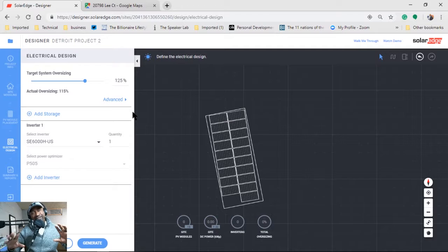365 days of irradiance, because in the summertime you have direct sunlight and it's high in the sky, but your modules get hot and they don't have as high a voltage. In the wintertime, you don't have as much irradiance, so they don't produce as much current, but you can have a scenario of cold weather. Cold weather actually makes them perform better.